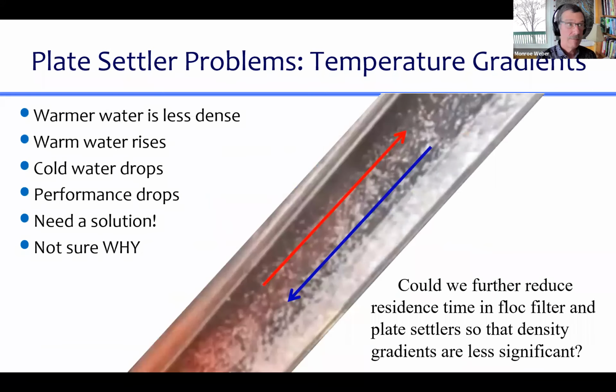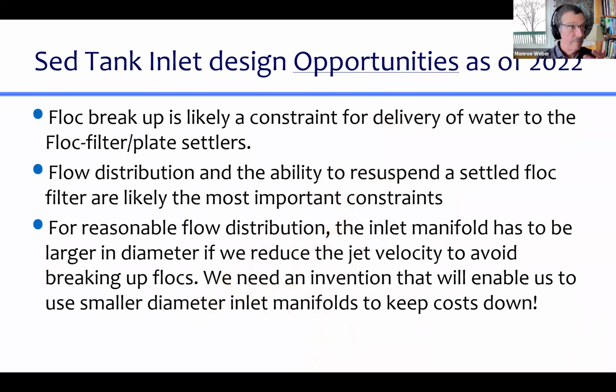And the problem is, we don't know how to solve this one. It's a problem with water treatment plants everywhere. We did advise that they stop cutting back the weeds next to the pipeline so that the pipeline would at least have shade, but that doesn't completely solve the problem because the environment is still warmer, and so the pipeline still warms up. And yeah, an ongoing problem that doesn't have a great solution.